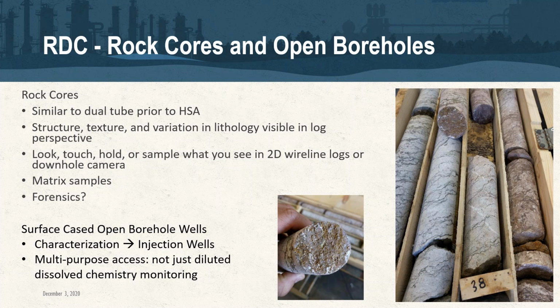And so it's quite crucial as part of any sort of remediation investigation plan to include with your geophysics some sort of coring schedule and actually having those cores available to interrogate the borehole prior to doing any geophysics or any follow-up investigation work on those.